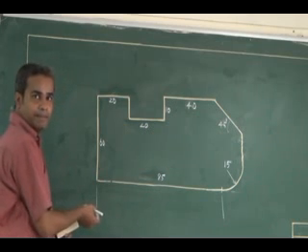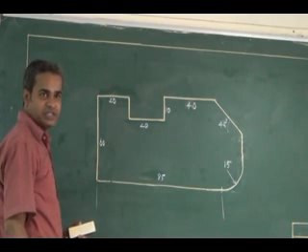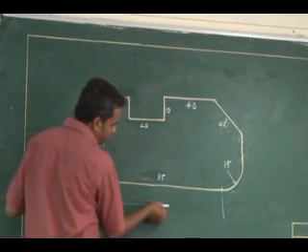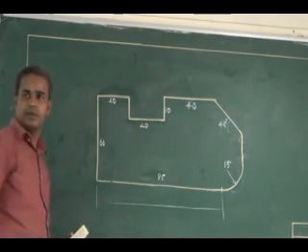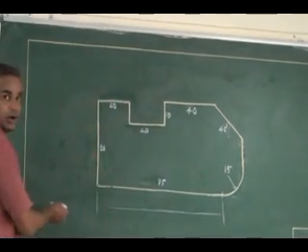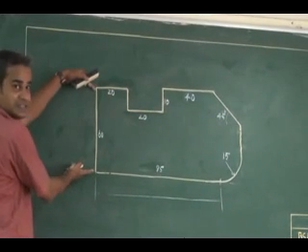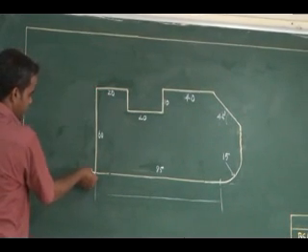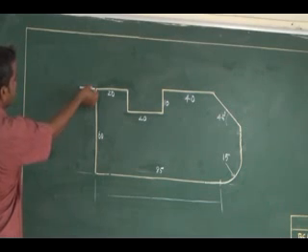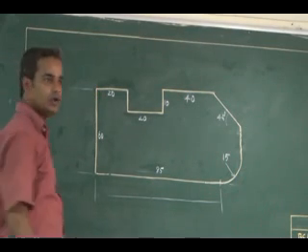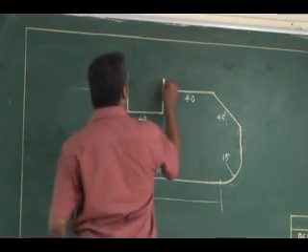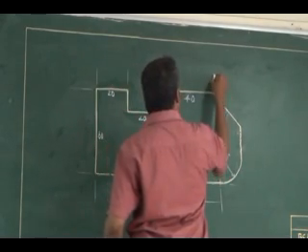Then I can draw a dimension line. It will be parallel to the object line. What is the gap? It is 10 mm. Then similarly I can draw an extension line for this entity, 60 mm, to dimension. I have to draw an extension line perpendicular to that entity, maintaining a gap of 2 mm. Similarly, for this 20 mm I have to draw an extension line.